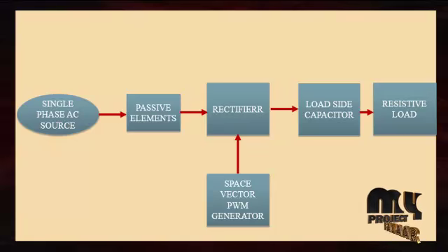We know that a rectifier is an electrical device that converts alternating current, which periodically reverses direction, to direct current, which flows in only one direction. The process is known as rectification. Physically, rectifiers take a number of forms, including vacuum tube diodes, mercury arc valves, copper and selenium oxide rectifiers, semiconductor diodes, silicon controlled rectifiers and other silicon based semiconductor switches. Historically, even synchronous electromechanical switches and motors have been used for this process.